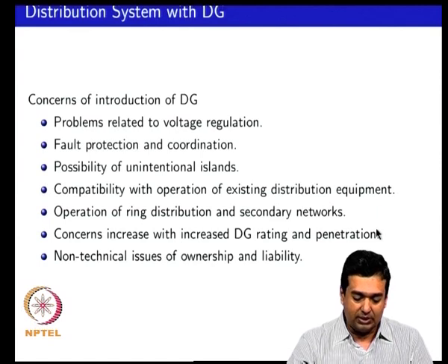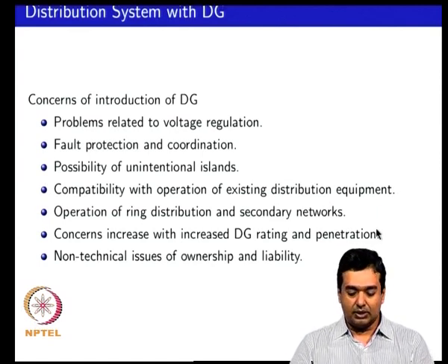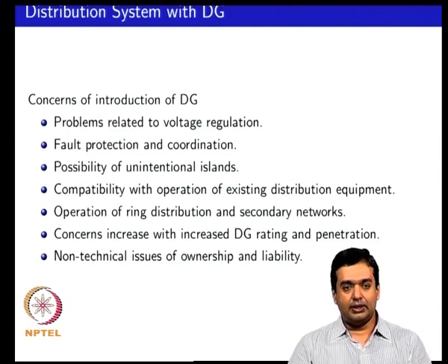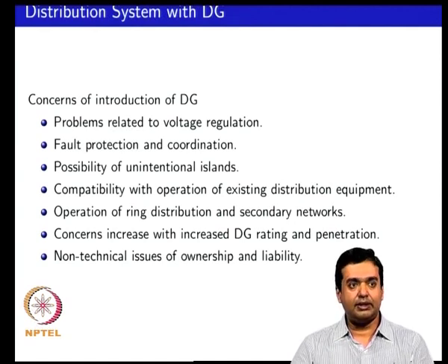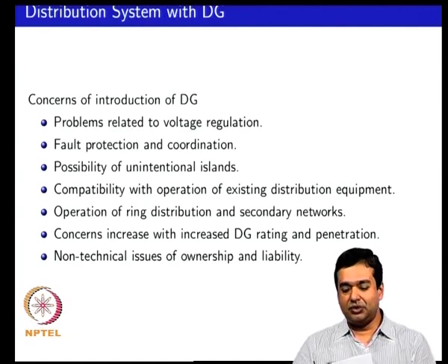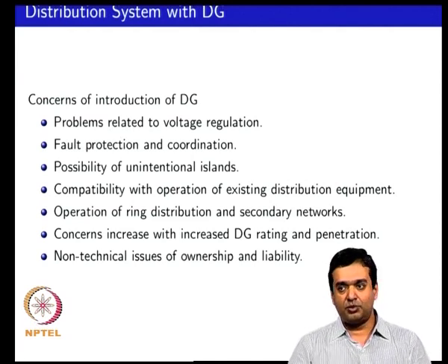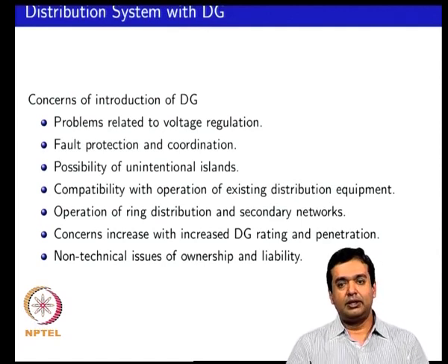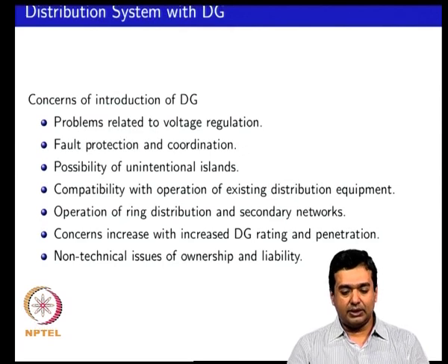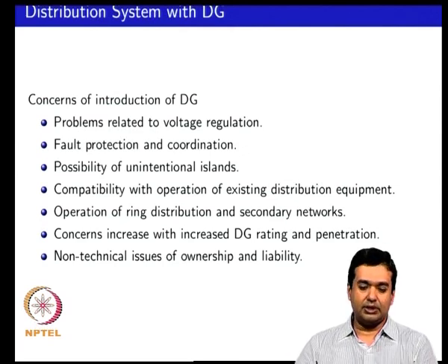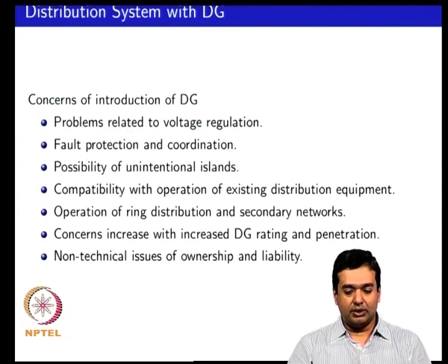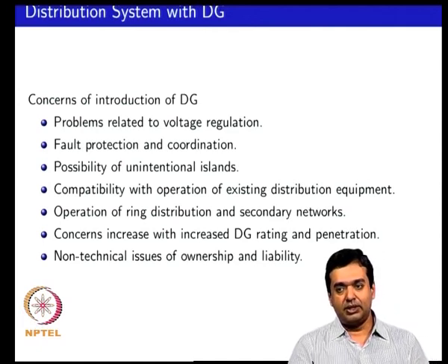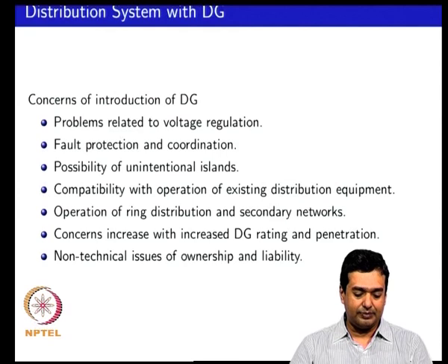There could be problems with open loop transformers, and on-load tap changing transformers with their open loop boost functionality. We saw there could be problems with series voltage regulators on ring feeders. These problems become more of a concern with more complicated distribution networks such as ring distribution or secondary network distribution. You might have problems with voltage regulators, network protectors, etc.